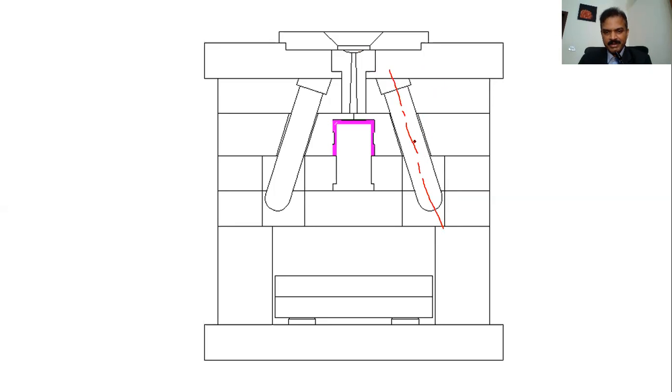This pin here, just imagine the plate is moving up here. It will move from here, right? So what will happen? When this pin is mounted at an angle, if it were mounted straight, nothing is going to happen on the slides. It will just draw out of the hole. Now the pin is mounted at an angle, and the hole cut in the splits is at the same angle. So when the pin moves up, it will pull the slides to the side, right?